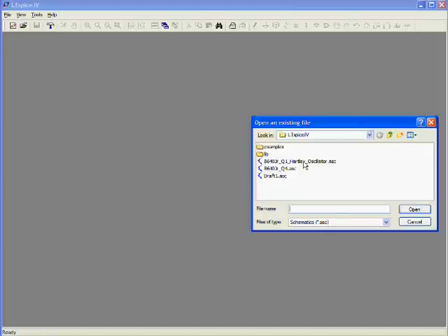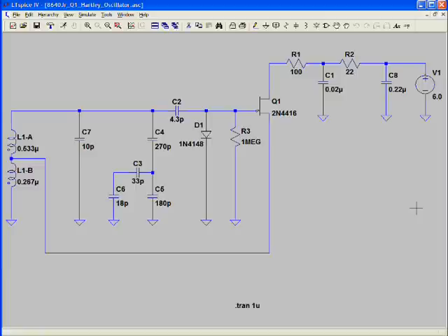This is my 8640 Junior Q1 Hartley oscillator, and here you can see that we've got our tapped inductor. On Wes's schematic he shows that as a single inductor, but in order to model it in LTSpice I created two separate inductors and connected them together basically. And there's some other things we're going to do a little later that will add some mutual inductance to those and make them a little more realistic.